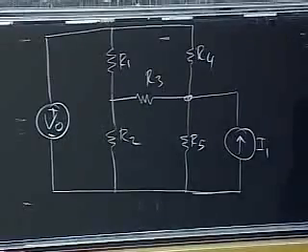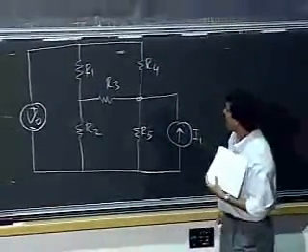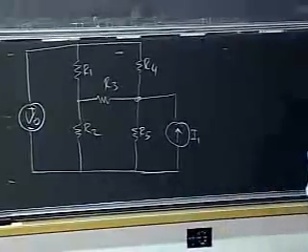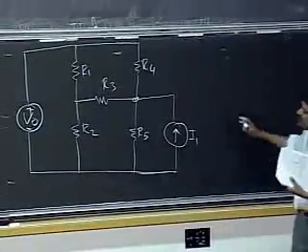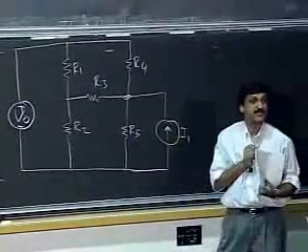Okay, so let's follow our method and just plug and chug here. So let's apply the first step. I select a ground node. It's a reference node from which I'll measure all my other voltages. Okay? Now, without knowing anything about the node method, try to use your intuition as to which node you should choose as a ground node.